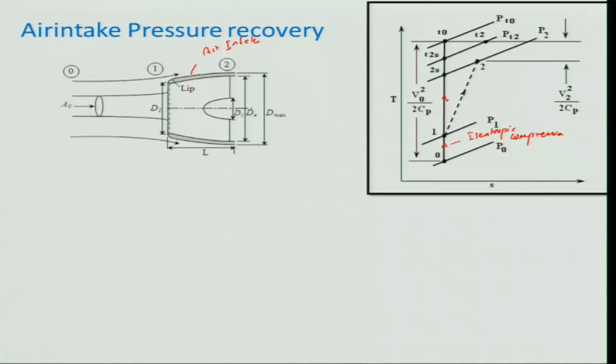So, therefore, it will be isentropic compression, but for the process P1 to Pt naught, if you look at Pt naught or Tt naught, this point is equal to Tt2. So, this process is basically the isentropic compression. But however, as the solid surface is there, it will have a lower pressure over here, Pt2, that means Pt2 is less than Pt naught.